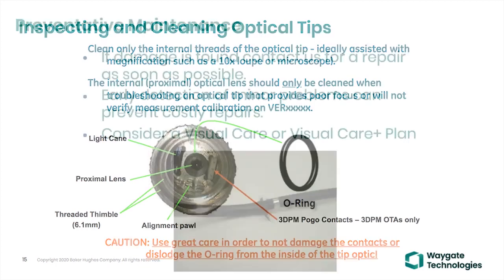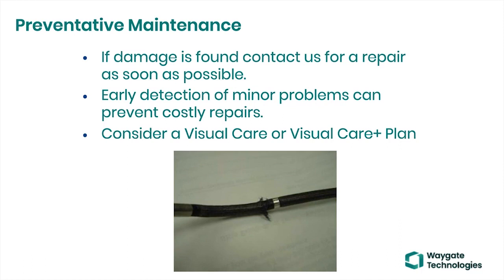So other preventive maintenance that you can consider is to look at the entire shaft, meaning the insertion tube, the bending neck, and the camera, and look to see if there's any fraying. You know, in the picture you're looking at here on the bottom, this is something that tends to happen on what's called an enhanced borescope inspection or an enhanced BSI.